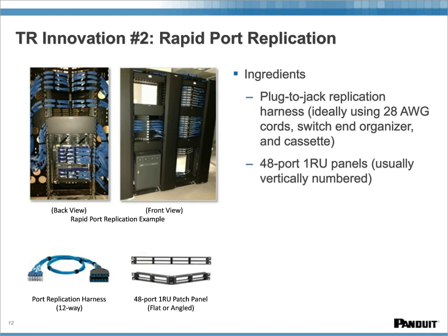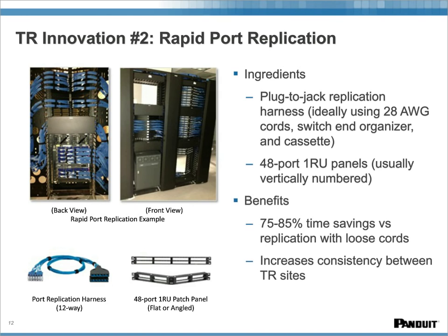Ideally, we will also use 48-port 1RU panels that can be vertically numbered just to match the exact switch port mapping, since switches normally are numbered vertically. The benefits seen in this application are even more time saved generally, and you might ask, well, why is that versus loose cords?